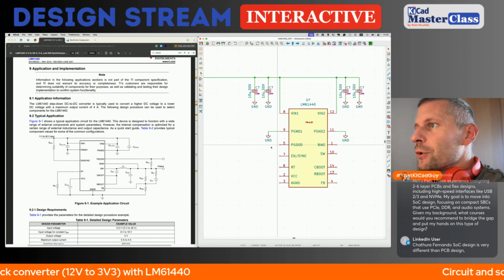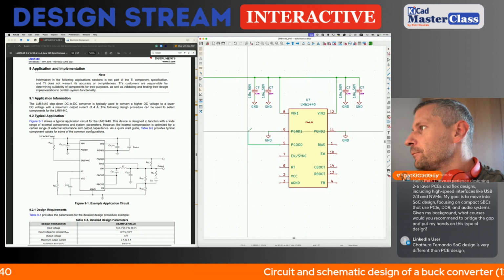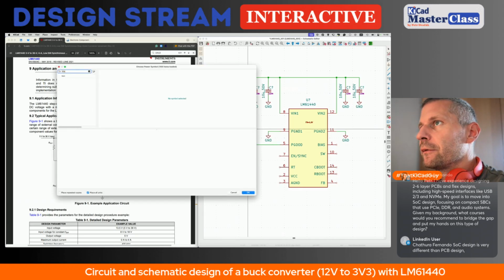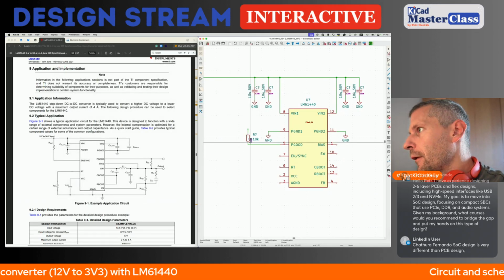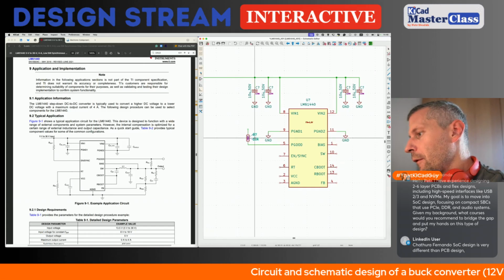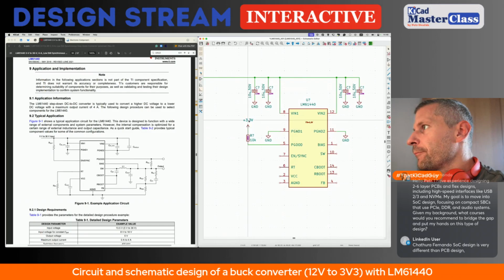We say power good. Power good is the output pin. So I will place the 10 kilohm resistor here, and the output will be 3.3.